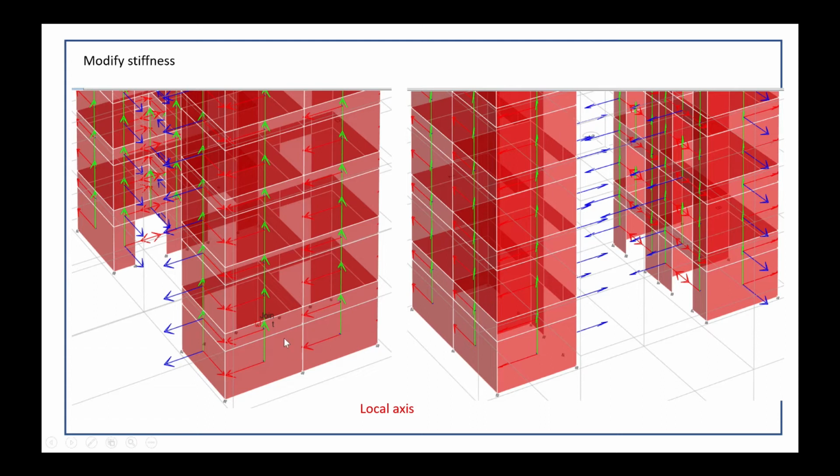It is a very common error for structural engineers analyzing stress results. To avoid the error, you should assign the local axis in the same direction, the same direction as the global axis. It's easier to verify. Now we will open ETABS to check it again. Continue to the next slide.